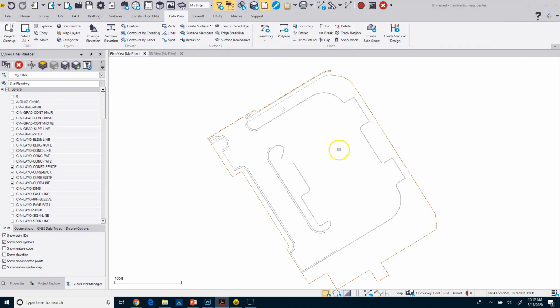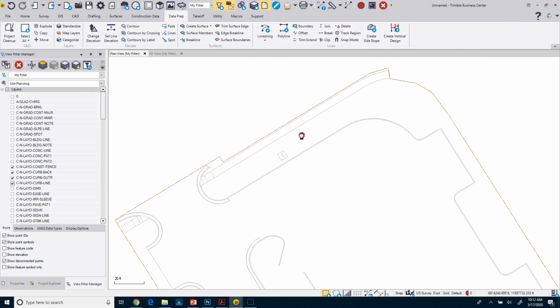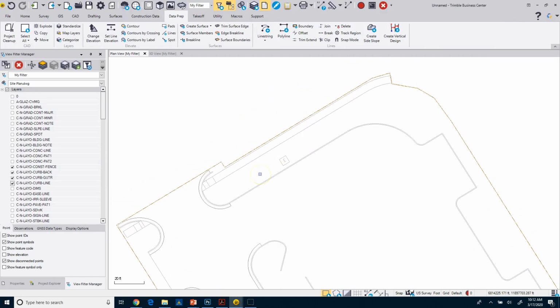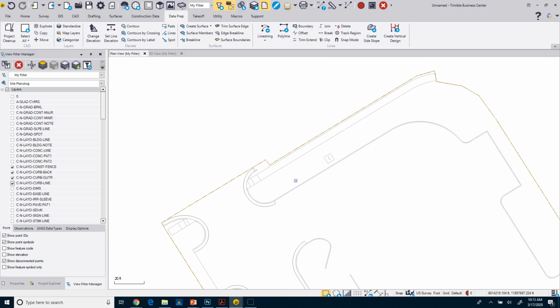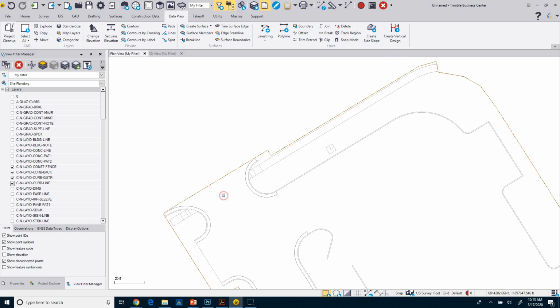By turning on those layers, I can see that they also have the sidewalk on a layer. So what I want to do is clean this up basically for stakeout. If I tell True to go stake out the sidewalk, they know to turn on that layer, sidewalk, and they can stake out this data. So basically I'm going to clean up some of this CAD, and we can do this multiple ways.